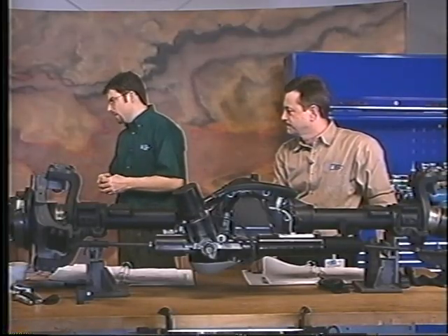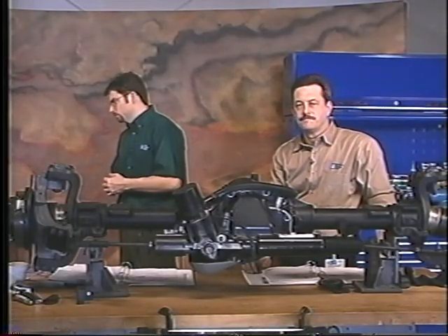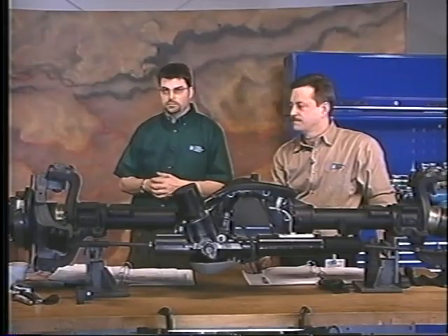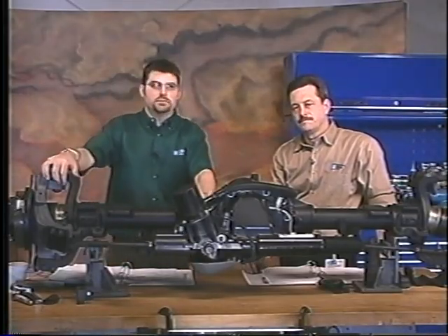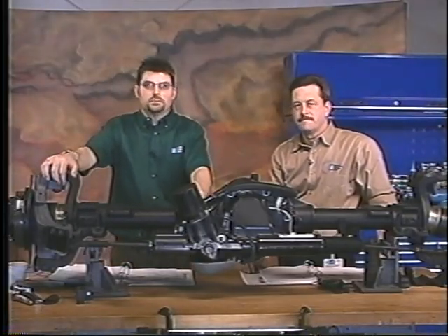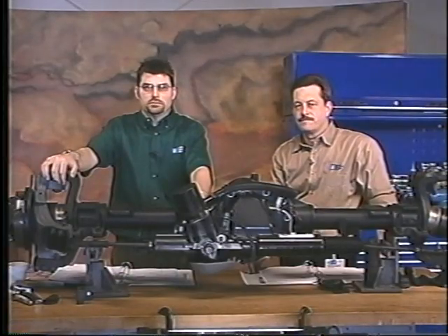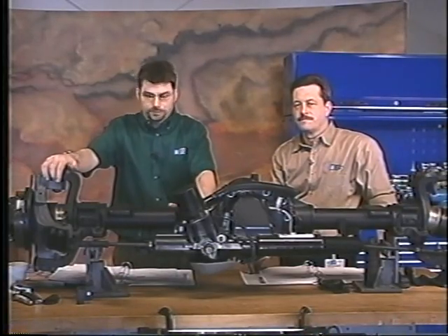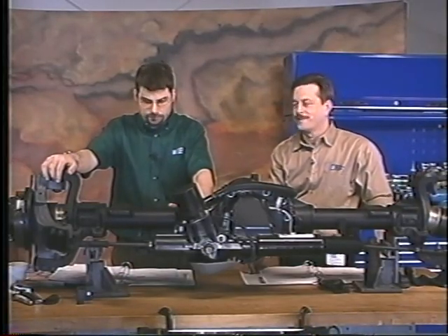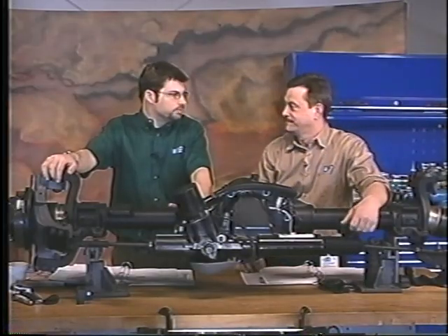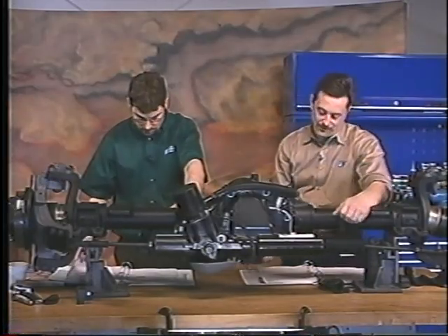Let's try Key Pontiac Nissan with Tim. Go ahead. Yeah, I would say the mode select switch, of course, because the module has to know which way to steer the wheels or not steer them at all, depending on what the operator of the vehicle is looking for. Absolutely. There we go. Driver's input into that system. Got to have that too. Good deal. Those are the ones we're looking for there.